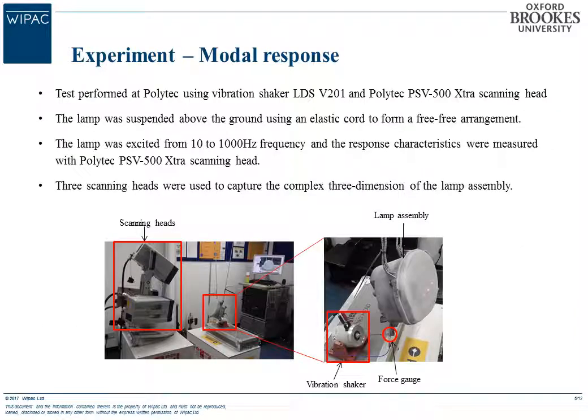Experimental modal response. The test was performed at Polytec using a vibration shaker LDS V201 and a Polytec PSV 500 Xtra scanning head. The lamp was suspended above the ground using an elastic cord, basically to form a free arrangement.